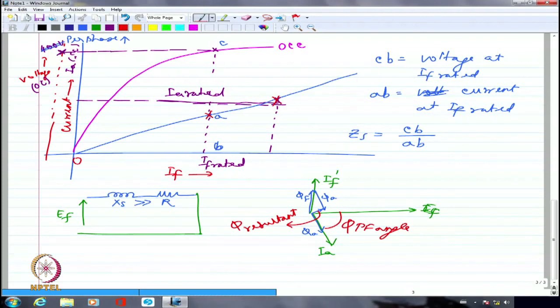That's one reason why, whenever you connect a capacitive load in a synchronous generator, again, we talked about this in the transformer. When we connected a capacitive load, we had negative voltage regulation. Right? At no load, if you had 230 volts, at full load capacitive, you would have 240, 250, 260 volts, whatever, depending upon how much current you have drawn. The same thing holds good in a synchronous generator as well. If I am going to have a leading load, I can have the voltage regulation to be negative. If I have a lagging load, the voltage will plummet. It will really go to lower values.